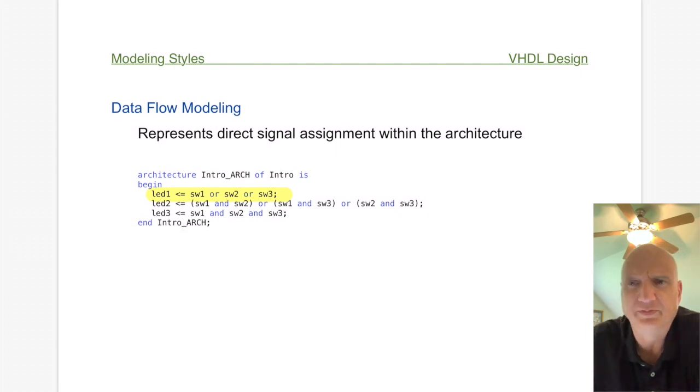The nice thing also about using data flow is it takes a lot of the work off the synthesis tool. In other words, the synthesis tool doesn't have to work as hard if you divide your design up and use things like data flow statements, and it can create more optimal hardware for you if you do that.